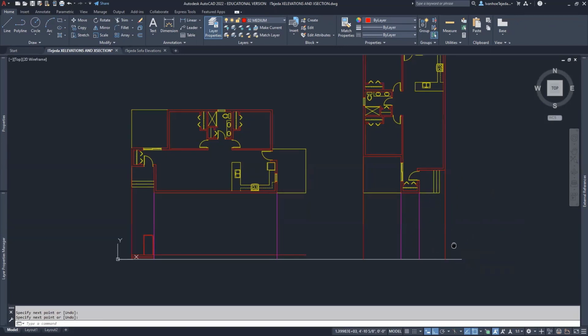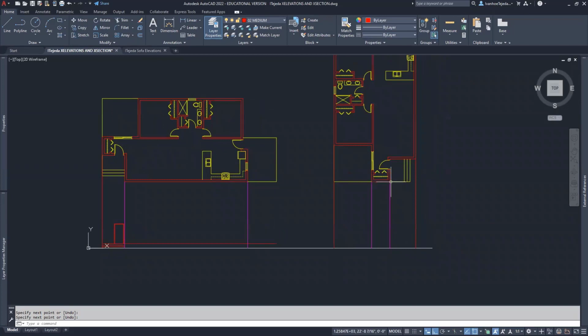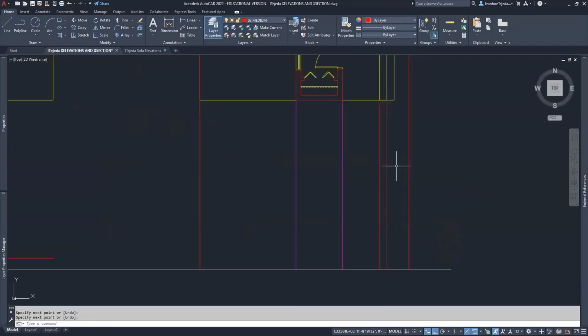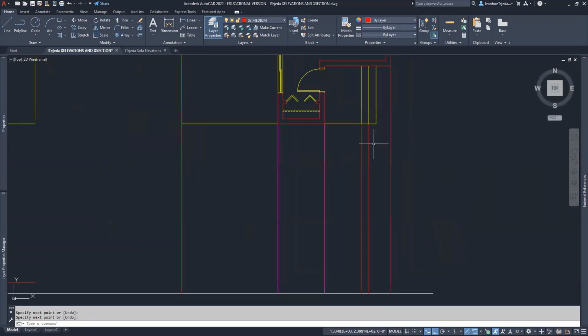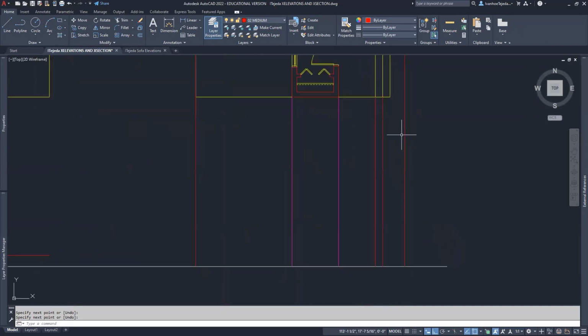And now for my stairs, yes, the stairs are in the foreground, but I want to make sure that my building is what stands out the most. So I'm going to stay on this medium layer and I'm going to construct the stairs. Let me draw a line from here straight down, enter, another line from here straight down, and I should zoom in. That way it's easier to see and not accidentally pick some other endpoint. And then L, enter from here straight down, enter.